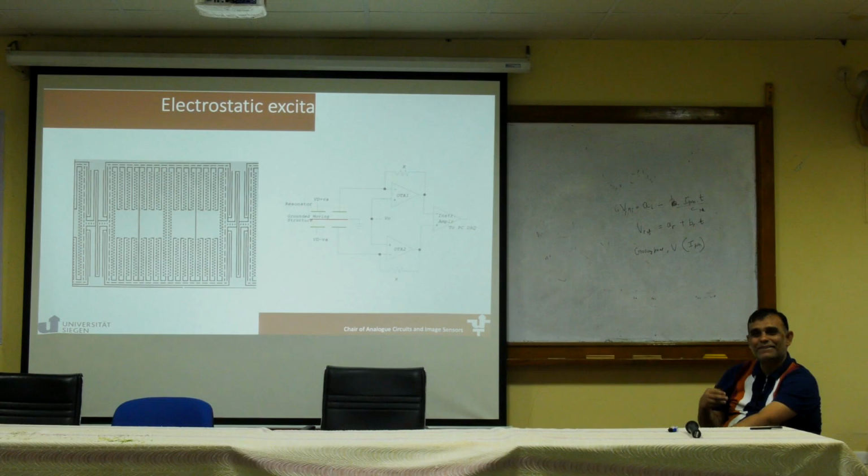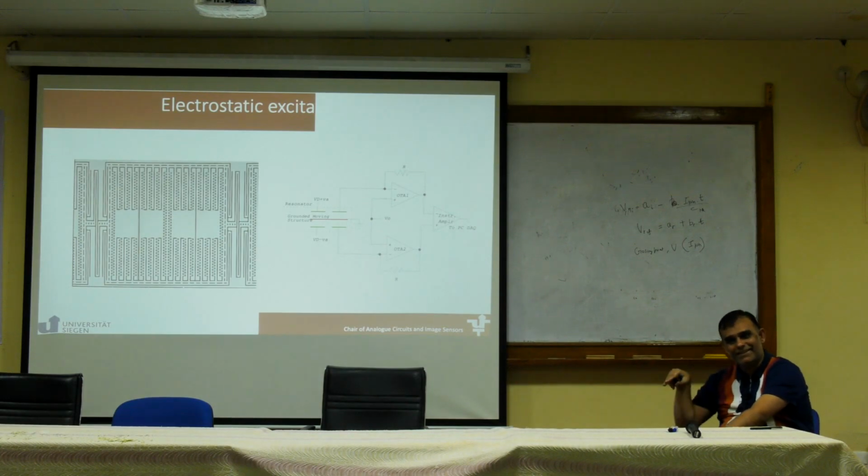So let's again ask the question, what's the current in a capacitor? How do we get that C dV/dt equation? CV is the charge in a capacitor. And we say dq/dt is current, so we say C dV/dt. But the actual relationship of current in a capacitor is C dV/dt plus V dC/dt. Are you with me? Or do you want to do it on the board?